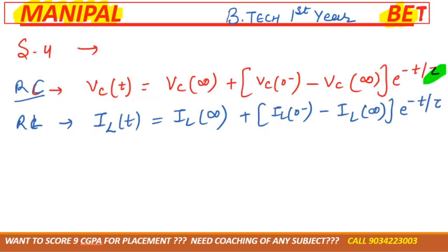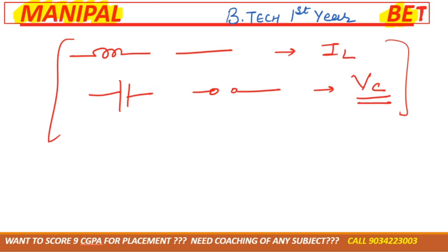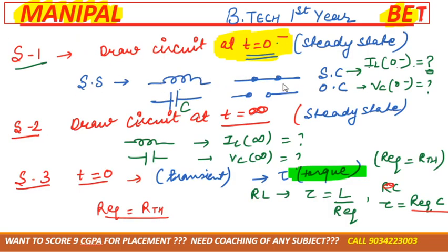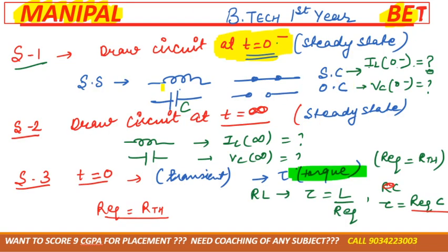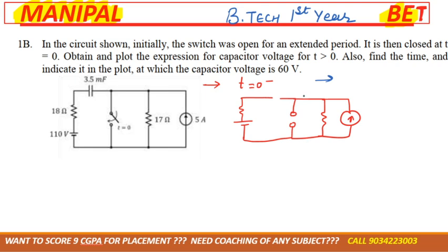Now, as I told you in the steps that if there is a case of inductor, then inductor must be short circuit and capacitor must be open circuit, right? So open circuit the capacitor also, okay. And in this particular case, as I told you, if there is a case of capacitor, what we need to calculate? Vc of 0 minus, correct? So calculate Vc of 0 minus. Wherever the capacitor was there, mark A and B. Okay, so Vc of 0 minus is equal to...